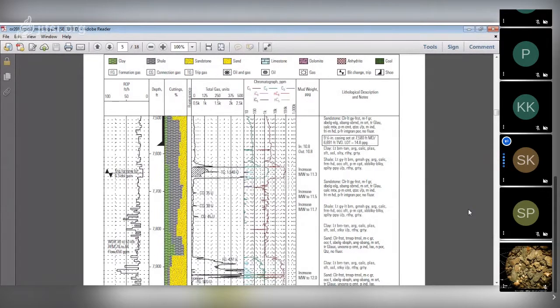And there will be the gas system, which is continuously running. Whatever gases are coming out of the hole flow through the flow line to the shakers, and on the shakers you will have a gas system which continuously stirs the mud and pulls out the gas.